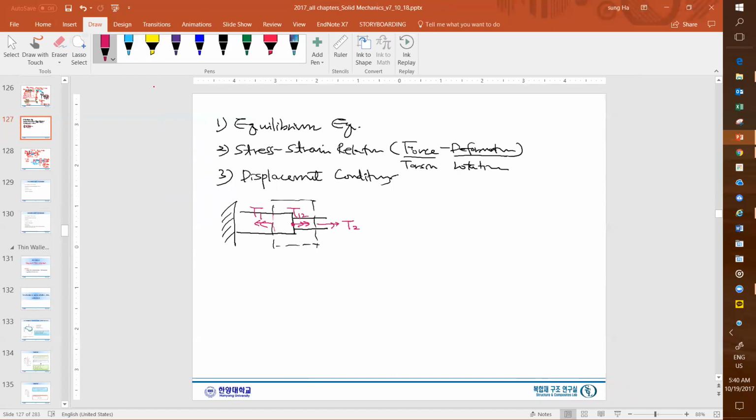We just consider only this section. So equilibrium-wise, the x-directional total torque will be T2 minus T1, this is the negative direction, plus T12, which is the positive direction, and this should be 0. So this is simply step 1, the equilibrium condition, and this equilibrium condition will be applied to every section, every connecting point, right? But I just wrote down the first one here.